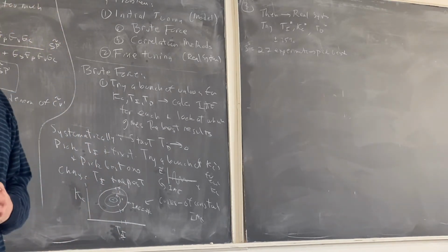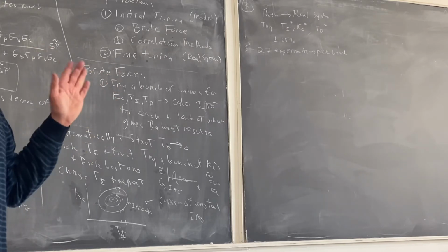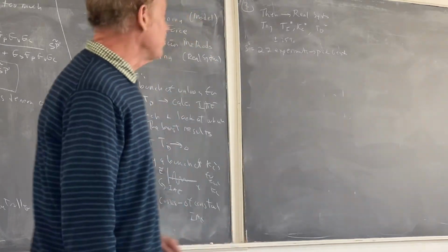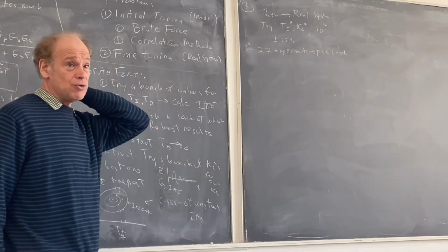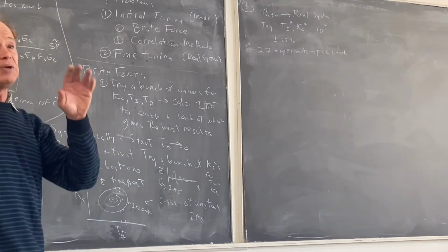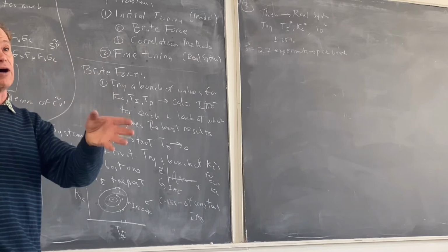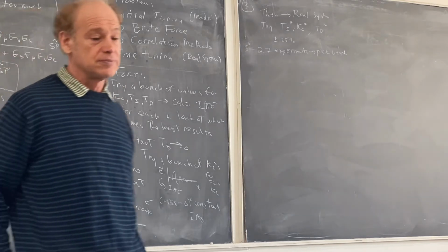Will there always be an optimal combination that's the smallest? No one says this has to work. You try it. There's no guarantee. Remember, parameter space is big, it's infinite. There are infinite numbers of these. So you have to be kind of lucky, and from experience, you know the ballpark of KC, TI, TD to choose, so that you have a good chance of getting something like this.